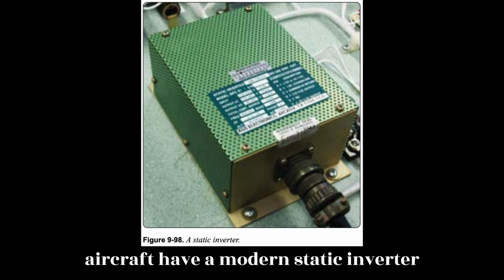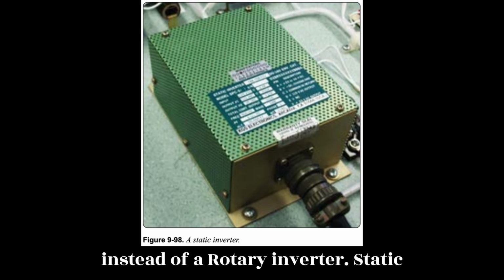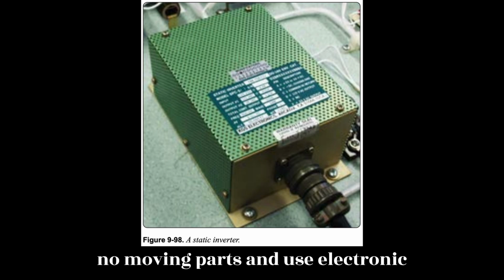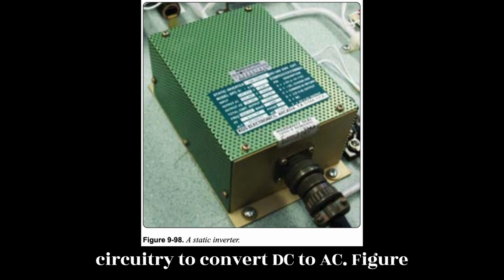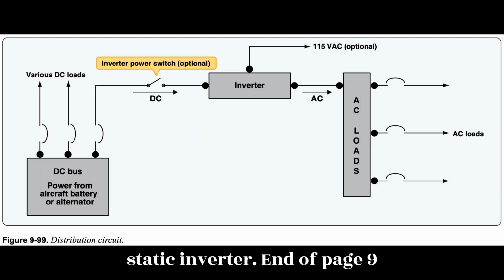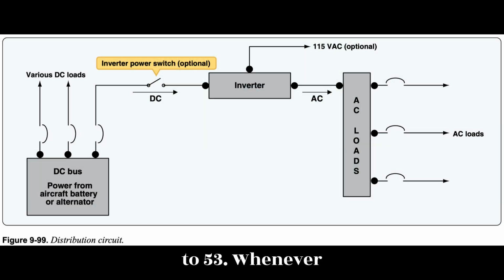Most aircraft have a modern static inverter instead of a rotary inverter. Static inverters, as the name implies, contain no moving parts and use electronic circuitry to convert DC to AC. Figure 9.98 shows a static inverter. End of page 9-53.